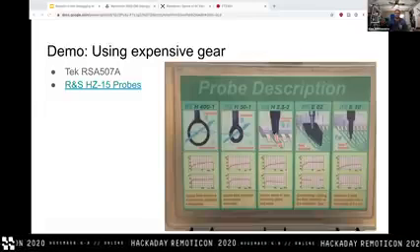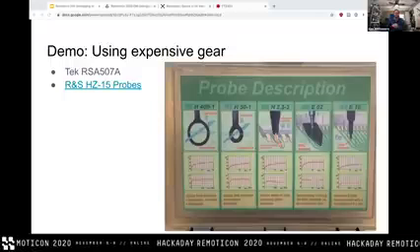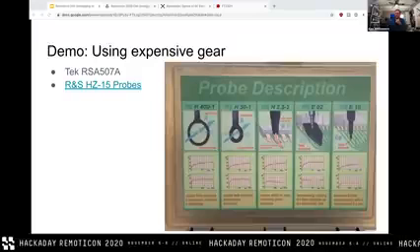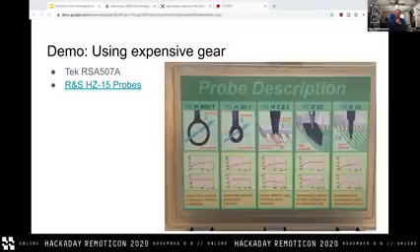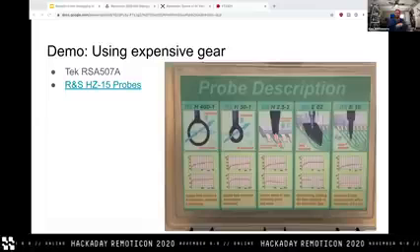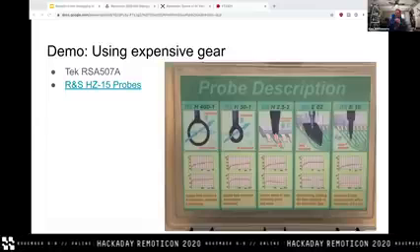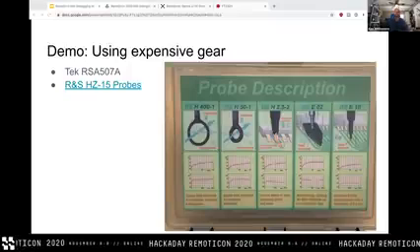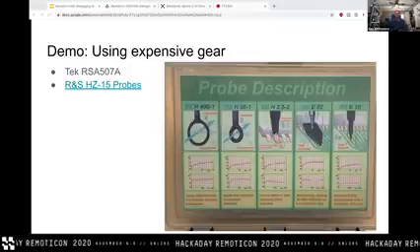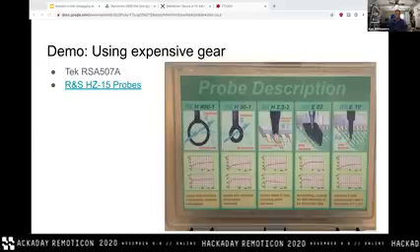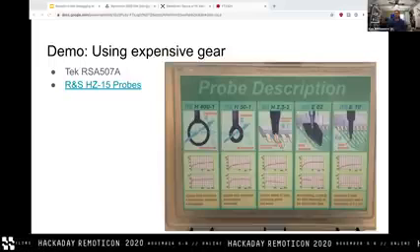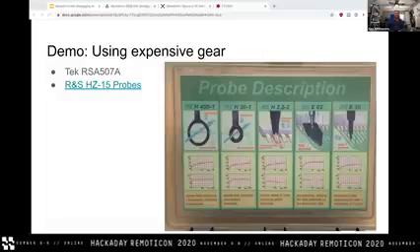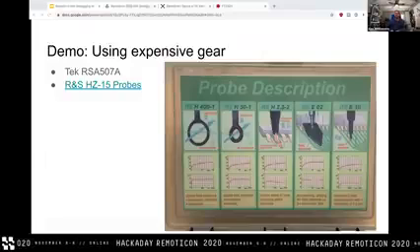Rather than sweep one frequency through, the RTL SDR we'll be using takes a 2.4 megahertz wide chunk of spectrum all at once, centered around your tuning frequency, and reflects that all at once, which is super great for zeroing in on a frequency that you already know is a potential problem, because you just tune to that frequency and then you can see in real time as you move the probe around exactly what that frequency is doing, along with potentially frequencies adjacent to it.